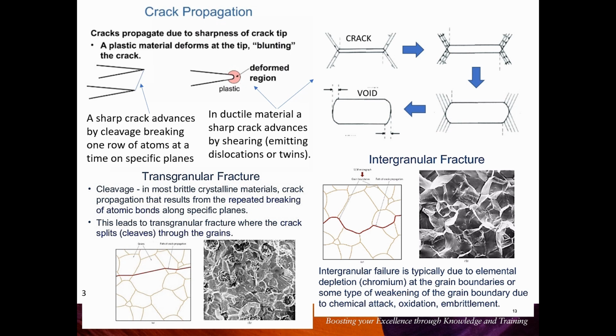So high temperature is not a problem, low temperature it is a problem. So that's enough of cleavage fracture, just to know what it is, and that we don't trouble ourselves with cleavage fracture when it comes to reactor materials, and especially not during operation in the reactor core.